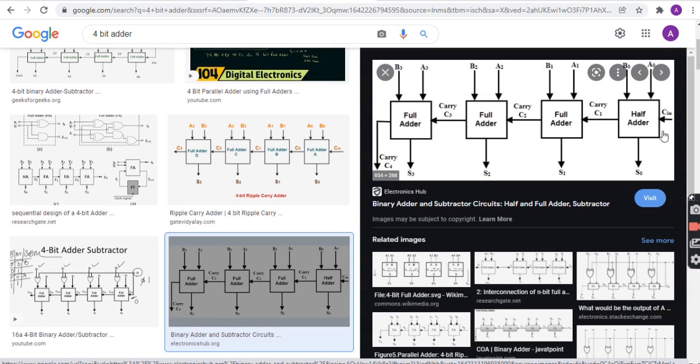Basically, you have to know the half adder circuit and the full adder circuit, how it looks, right guys? It's only a block diagram, which is very complex. It will become a circuit. Like here, half adder means 1 XOR gate and 1 AND gate, right? Right guys? Please try to respond. Yes, sir. So you require these things for a 4-bit adder.